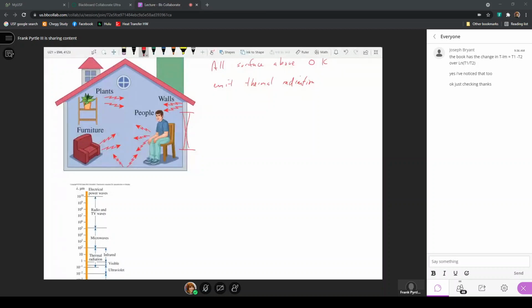So if you get to a window that doesn't have drapes on it, that cold glass is at a much lower temperature than the drywall you were previously walking past. And if your arms are uncovered, the heat flux by radiation from your skin to that cold window is much greater than the heat flux from your skin to a warmer drywall.